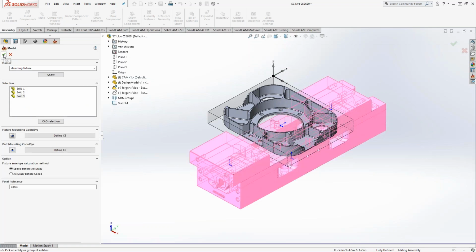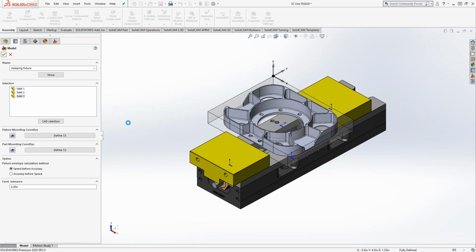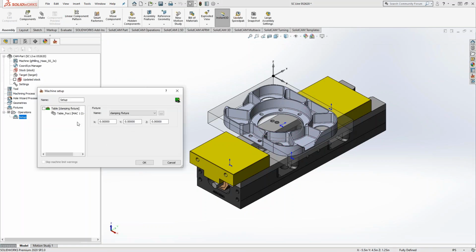What this will do, however, is if you need your machine setup to be accurate, by doing it this way, when we look at our machine preview, everything is going to sit correctly. There's no need to modify, if necessary, for things like 5-axis or your machine sim. These can all stay at 0, because now these are basically how far away the coordinate system is sitting from the machine 0. Since I did all those coordinate systems just now, everything sits correctly in the machine preview once it pops up.